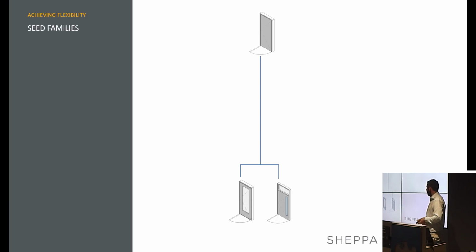You start off with a seed family, or an initial family. So right at the very top there, the very first one that I built was a single swing blank door, kind of the very basics. That was the absolute beginner. For that, I loaded all my data in there. I added my functionality for door swings and visibility controls and stuff like that. And from that, I was able to create different variations, different leaf types, and so on.